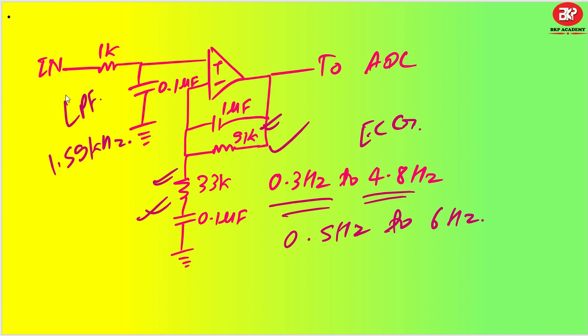So the first step will be a low pass filter, then put a buffer, and this buffer is acting as a low pass filter also and amplification also. So this is the meaning: not just a buffer, it can act as an amplifier also, and then you send it to your ADC. That's another step. This can be your third recommended step. So based on the requirement, you can utilize any of these input stages for your ADCs.